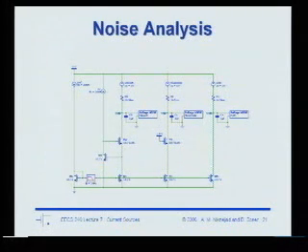The reason that we use this transistor is we want to see how much noise this transistor introduces into the overall circuit. In reality, you're probably going to use something more sophisticated than one transistor as a gain booster, just to get more gain. So whatever noise is introduced will be even higher than what we're showing here today. Okay.